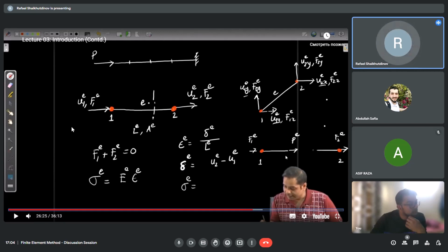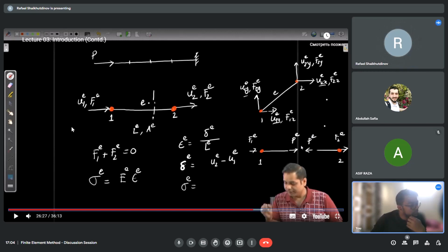To consider equilibrium, he divides this and uses this internal force, directing it as we did in strength of material, so they are directed in the right way. But you know from strength of material that P1 is equal to EA du dx. So from my perspective, we cannot consider this term as a boundary term.